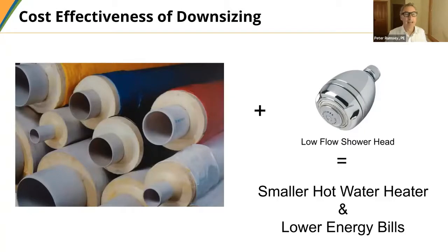And so this is where load calculations and loads come together with architecture. The type of glass, the amount of insulation, those are architectural decisions, not engineering decisions, typically, but they impact the loads and the size of the cooling system, right? So this is where architects and engineers need to work together.